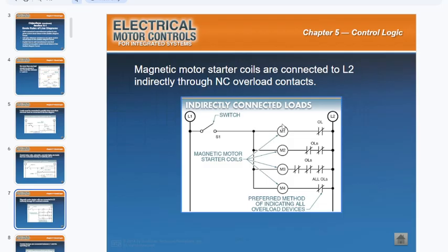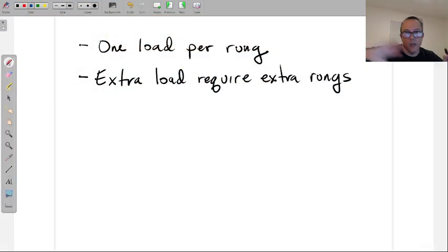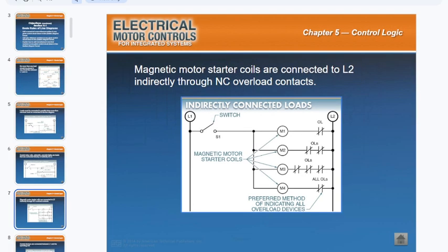Well, if one shuts off, you don't want these boxes to keep coming from 2, 3, and 4 and just piling up and falling off all over the place. You want, if motor 1 goes down, everything behind it to shut off as well. So that's a way, and a design, in which you can get that effectively done.